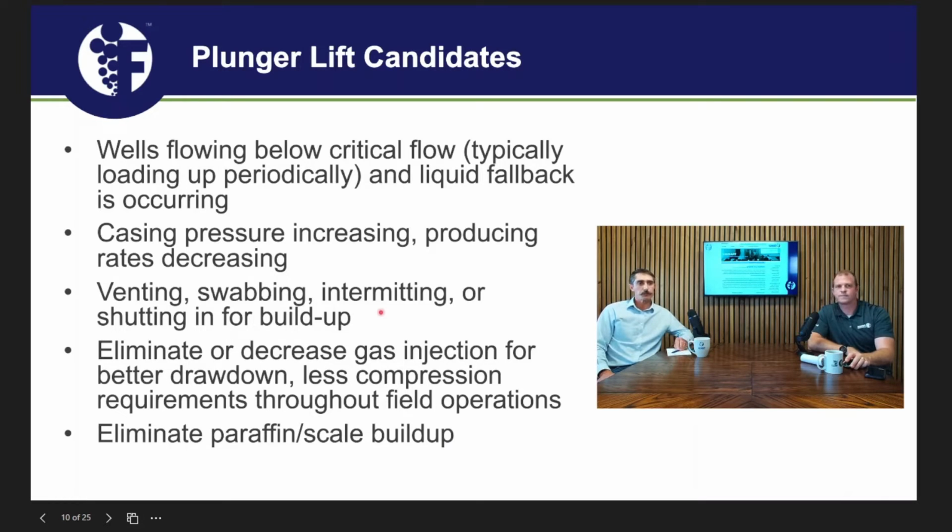Okay. Or any well on gas lift, and I don't know how much we'll get into this today, but I've been asked a lot, when is a gas lift well ready for GAPL? Going from continuous gas lift to gas assisted plunger lift. With wells on gas lift, I've seen a lot of improvement in efficiency from adding that plunger. And then anything with paraffin or scale buildup, we've seen that a lot.